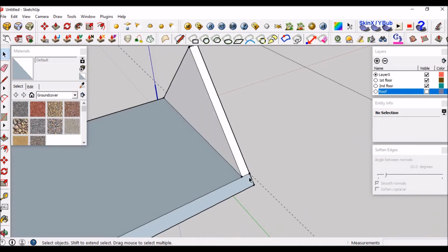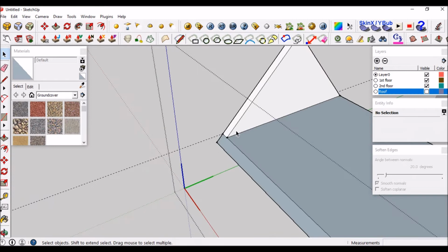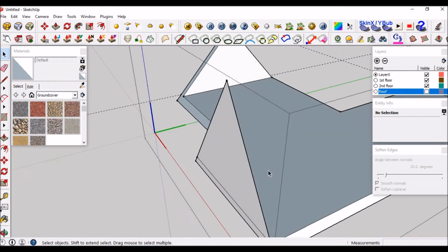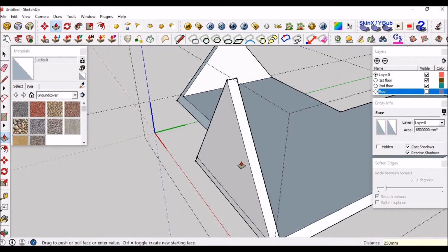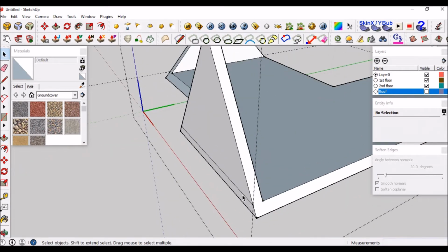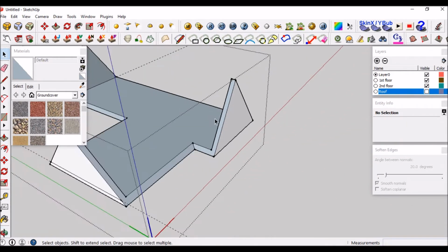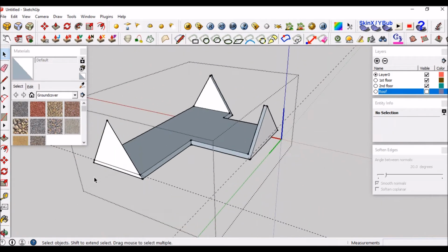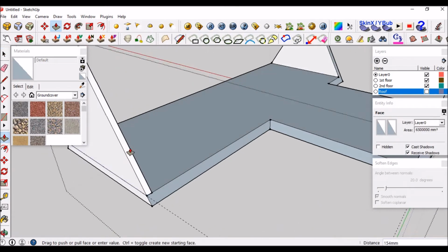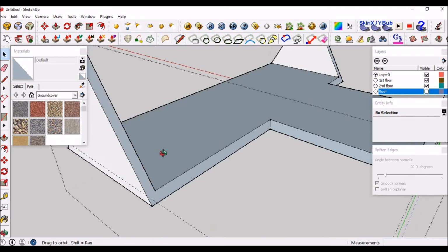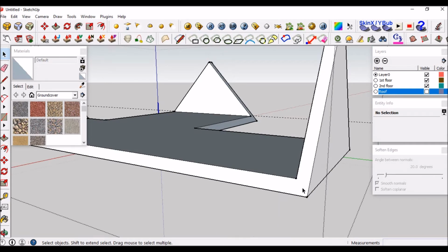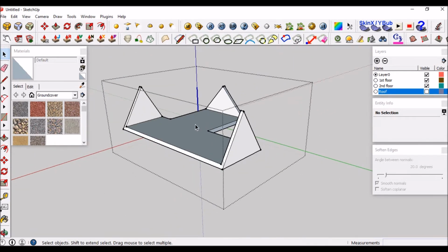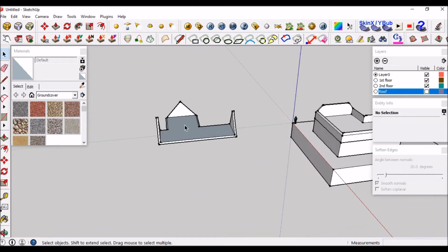So now all we have to do is, these are walls, give them some thickness, 250. Delete these lines. I can't stand too many lines. It's a problem. So delete, delete. Also, eventually it will make a difference in how large your file will be. But also, I just can't stand them. 250. Delete, delete, delete, delete.